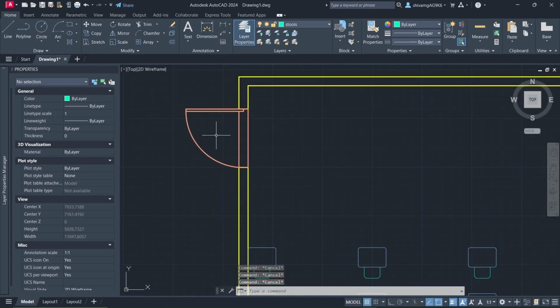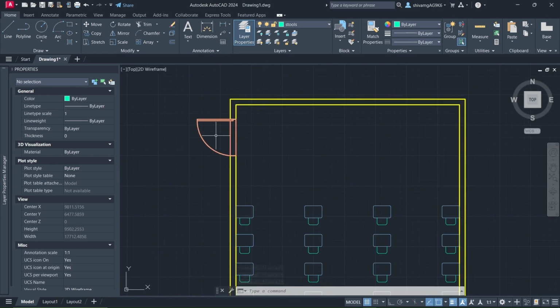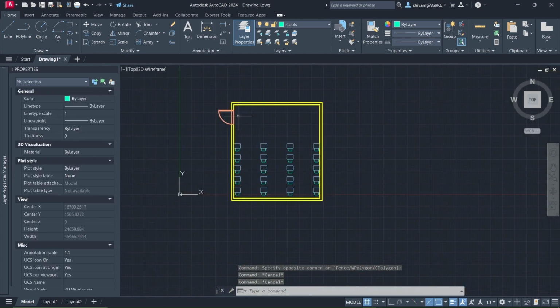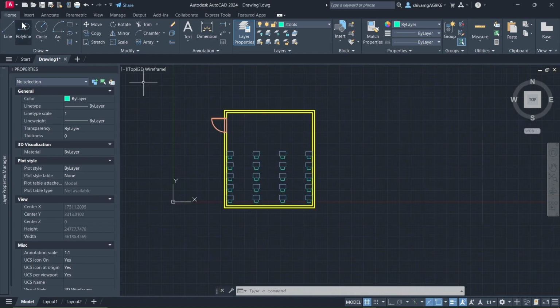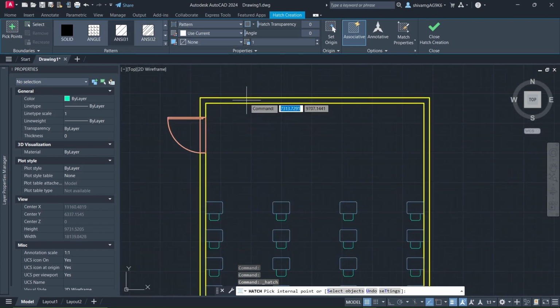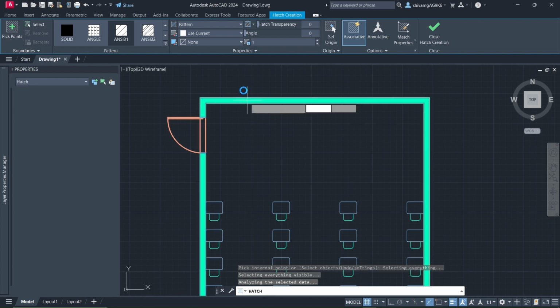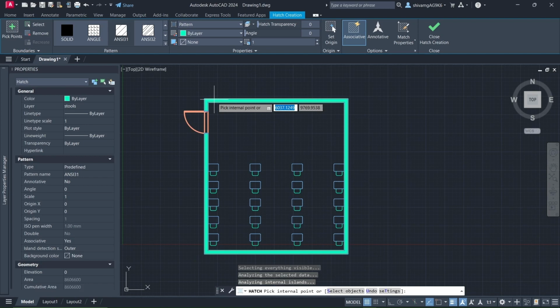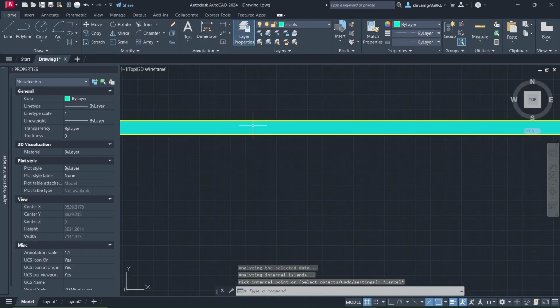In explode command, I didn't tell you that you can explode polylines, blocks. As this is block, you can also explode this. Okay. So now let's use hatching. Click on hatch. So for brick we use this hatching pattern. So use this. Click here, and here you can see it is selected in whole drawing. Okay.